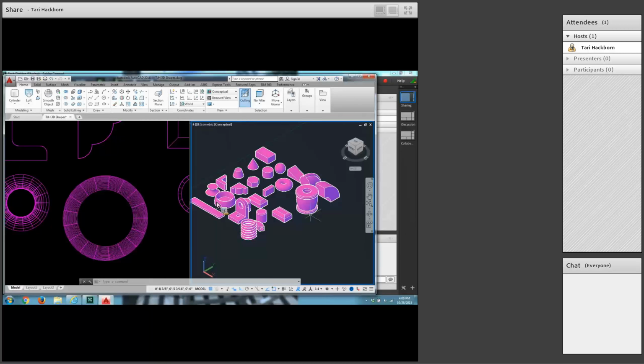You have a polysolid button. It's up here next to the solid modifying commands. That's it right there. Cool. Okay. It says to first select the height option. Okay, that's down here. And type a 1/2 inch and enter. And then pick the width option and type a 1/4 inch and enter. Oh, this is tough. And then it begins at 8.5, 4.